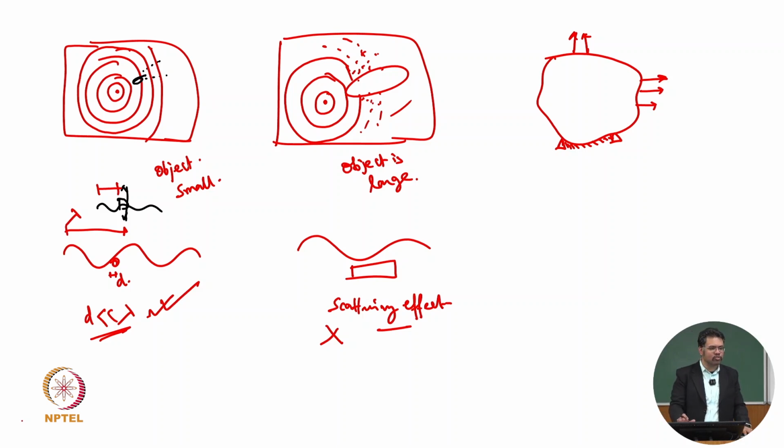What type of thing will you look for? Suppose it is a 2D plane stress or plane strain, we are more interested in seeing it as a continuum. So if somebody gives me Young's modulus and Poisson ratio, I would be very happy. I will just make a stress strain matrix, then we will have a strain displacement matrix and we will solve that full thing.